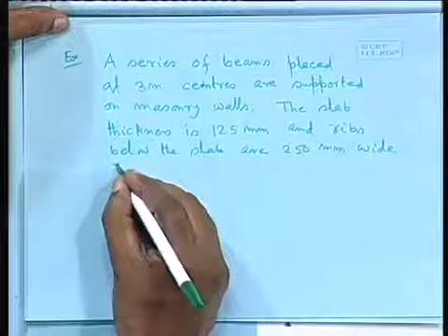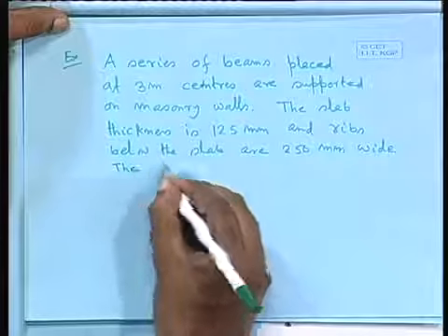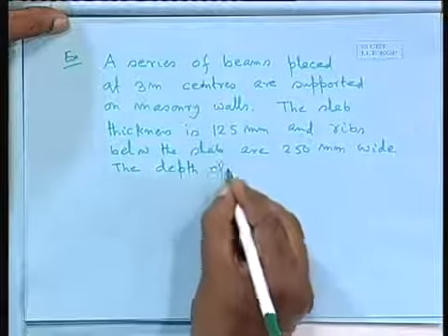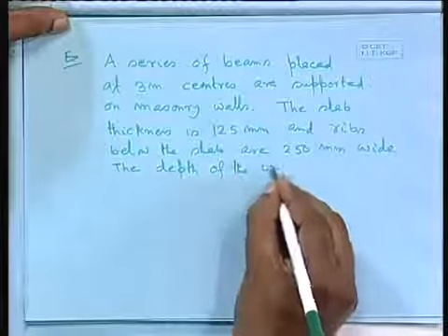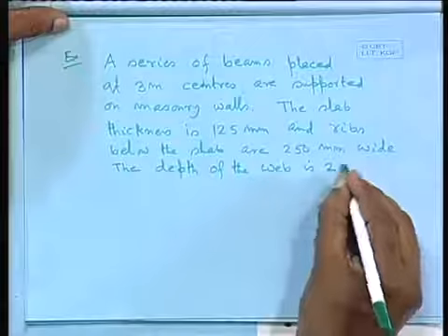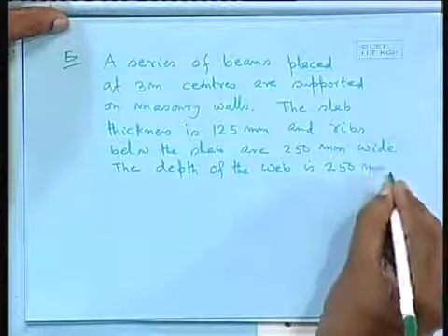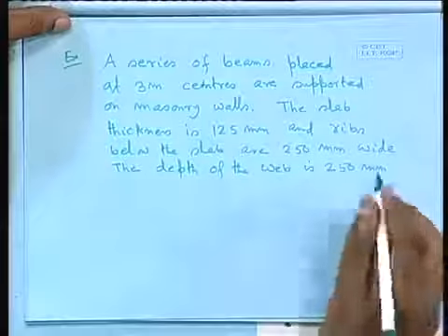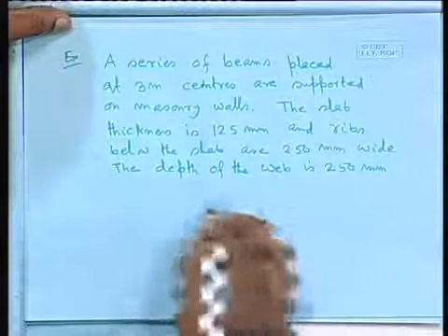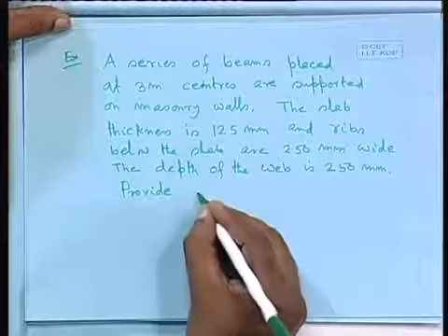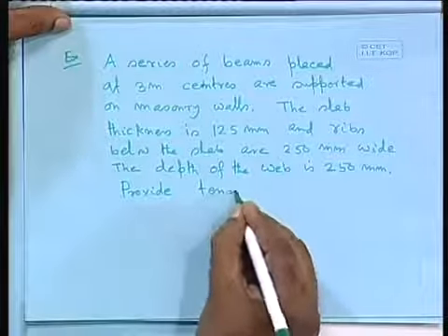The depth of the web, let us consider, is say 250 millimeter. We are taking that, we are assuming, if it is not then we shall change it, but we are taking that say 250 millimeter. Provide tensile reinforcement